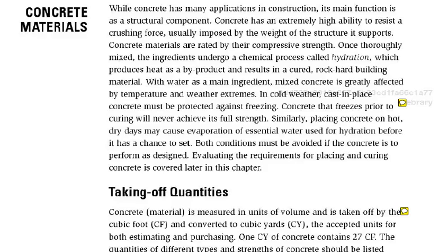If it gets real cold, you can place concrete, but you need to cover it, you need to insulate it. Potentially, if it's going to be real cold for an extended period of time, you're going to build a cover, and you're going to put a salamander or a heating unit in the covered area to keep the concrete warm. On the other hand, if it's too hot, the danger is water evaporates, so there isn't enough water for hydration to take place, and so you have to be very careful.